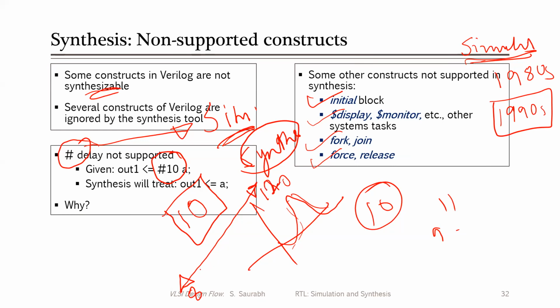So we always design within a range with some margin, right? And that is possible, and that is what is ensured also by static timing analysis that we'll be looking into in tomorrow's lecture. So we always design a circuit to have a delay within some range, and that is not impossible. That is very much possible, and that is what we do, right?